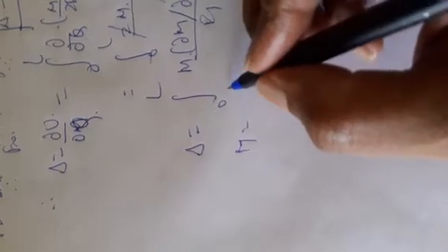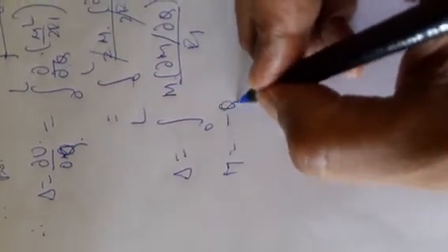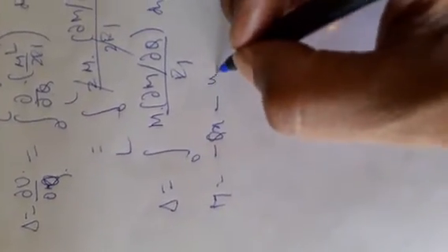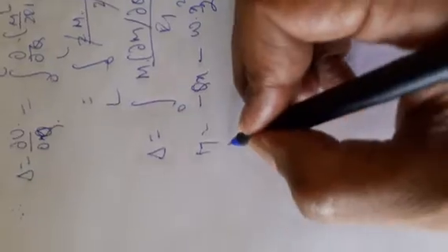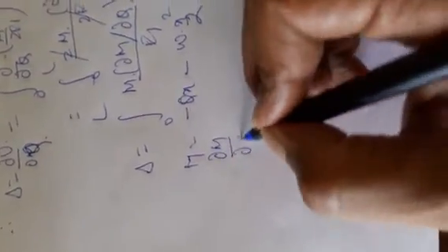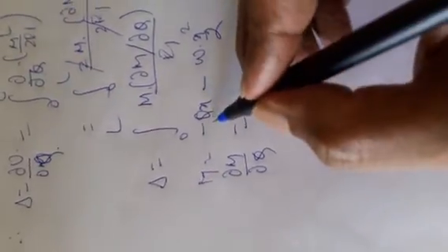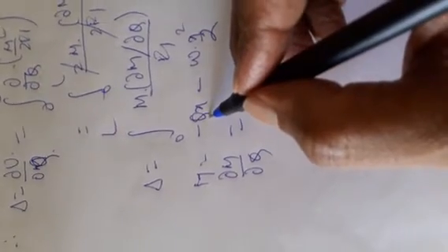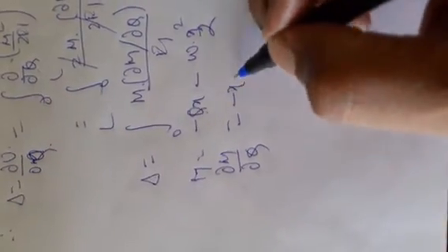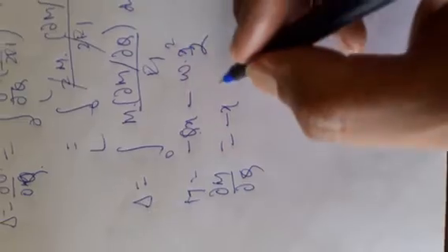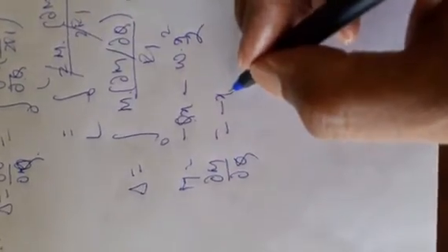So M is equal to minus Qx minus Wx square by 2. So let me find dou M by dou Q. Here dou M by dou Q is with respect to Q. So I am left with minus x. Here there is no Q term, so this is 0. So dou M by dou Q is minus x.